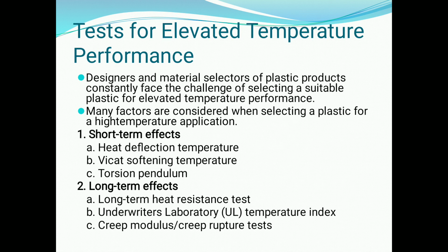And the next heading is tests for elevated temperature performance. Designers and material selectors of plastic products constantly face the challenge of selecting a suitable plastic for elevated temperature performance. Many factors are considered when selecting a plastic for high temperature applications. First one is short term effect and second one is long term effect. The short term effect covers heat deflection temperature, Vicat softening temperature and torsion pendulum, while the long term effect comes under long term heat resistance tests, underwriters laboratory test, and the creep modulus or creep rupture test.